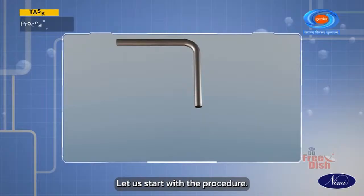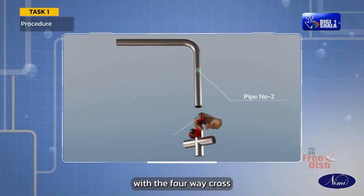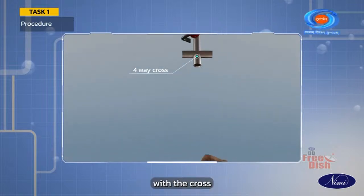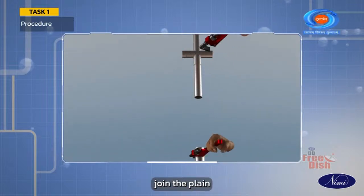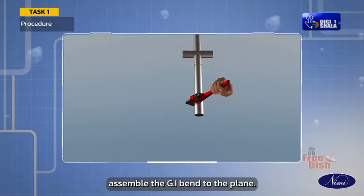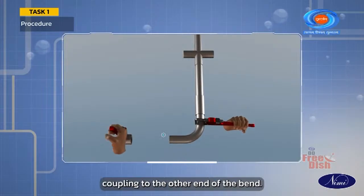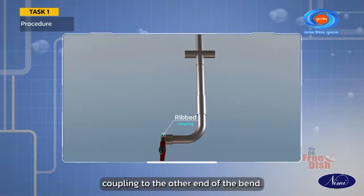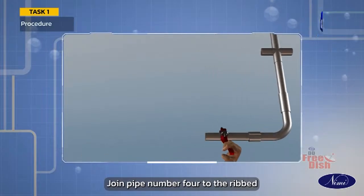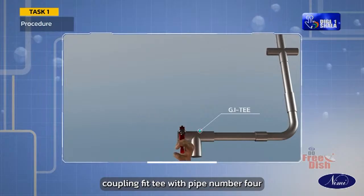Let us start with the procedure. Join pipe number 2 with the 4-way cross. Fit pipe number 3 with the cross. Join the plain coupling to the other end of the pipe number 3. Assemble the GI bend to the plain coupling. Fit the ribbed coupling to the other end of the bend. Join pipe number 4 to the ribbed coupling. Fit T with pipe number 4.